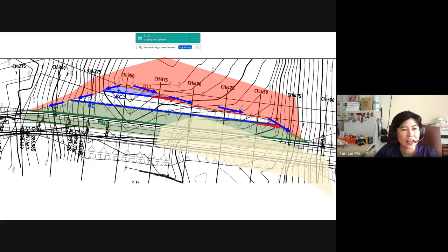Okay. I imagine when rain falls, the rainfall runoff direction will be like that. Then eventually it will come into like that. Here, I imagine it's going to be going to that area that would not go into this drain here, interceptor drain. So therefore, this is how I determine this area.